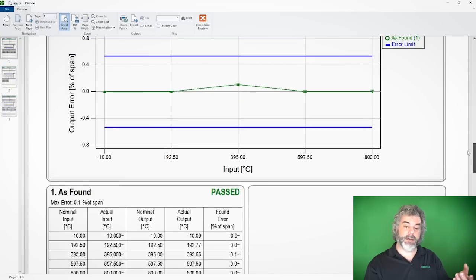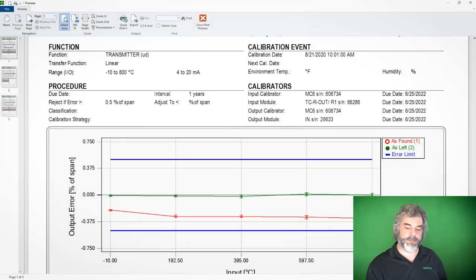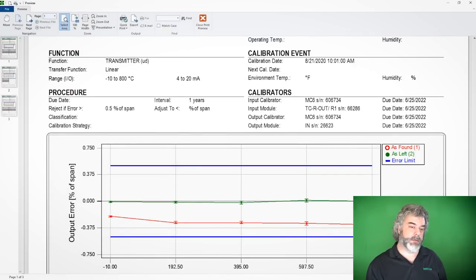Temperature indicator. All right, so this is our temperature. And you can see there's lines above and below each test point. That's the calculated uncertainty of the test standard that was used. So the MC6 is putting those bars. You can turn those on or off. It's just a checkbox in the options. Let's see, what is the final...